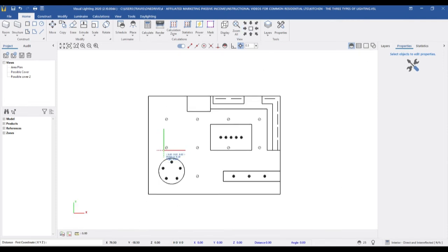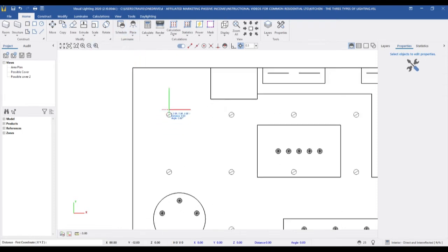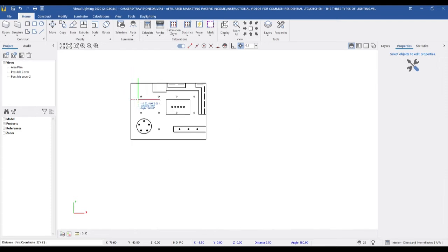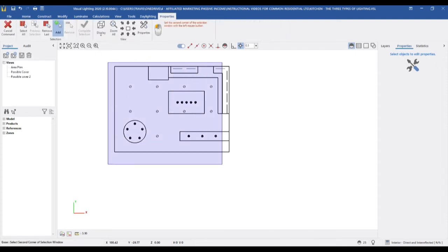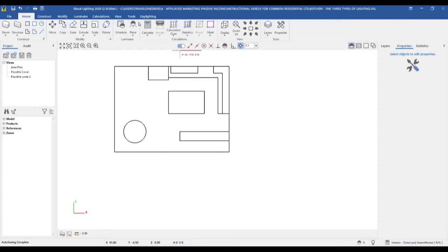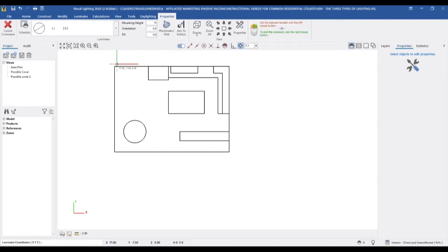And we usually want to consider the spacing of the light that's closest to the wall. So your starting and ending point is going to be about half of whatever your spacing is for the rest of your can lights. This is because of the max spacing and the spacing criteria, we don't have another can light there, so we want that to be half. So in this case, we'll do 3 to 5 feet. I think in this layout, for those of you watching on YouTube, it's 4 feet on average from the cans that are closest to the wall.